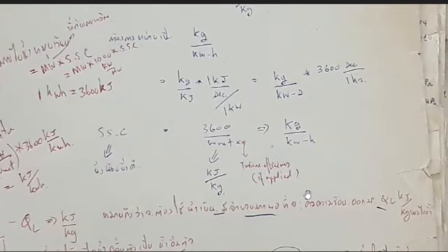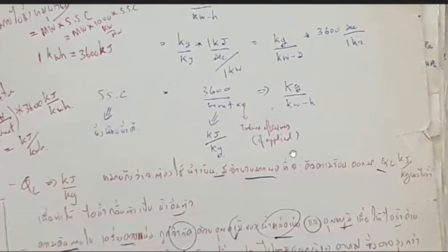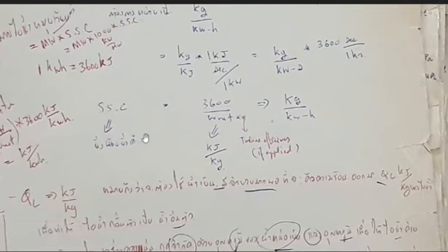That's not something to be worried about. Just know that the formula for specific steam consumption is 3,600 divided by work net. And maybe if we apply the turbine efficiency, we can multiply that here.